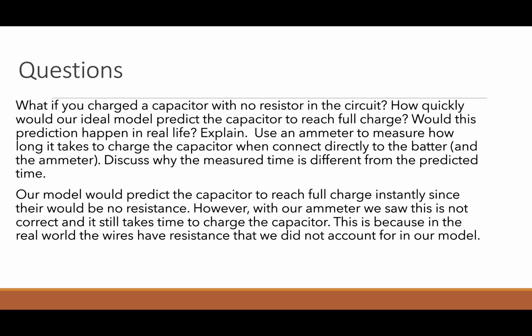Our model would predict the capacitor to reach full charge instantly, since there would be no resistance. However, with our ammeter, we saw that this is not correct, and it still takes time to charge the capacitor. This is because in the real world, the wires have resistance that we did not account for in our model.